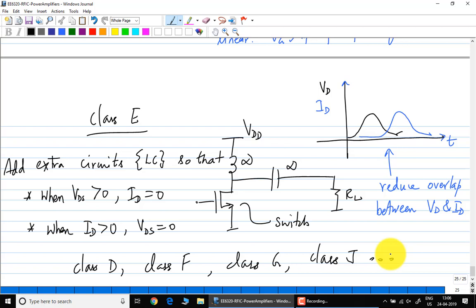I think linear PA is more relevant to the aim of this course, because going forward, the majority of high data rate communication will end up having information in both amplitude and phase. Therefore, you will need a linear PA coming out of the CMOS chip to drive the off chip. The power levels are high enough such that you can't even imagine driving it with CMOS, but you want to put out just a few milliwatts of power.